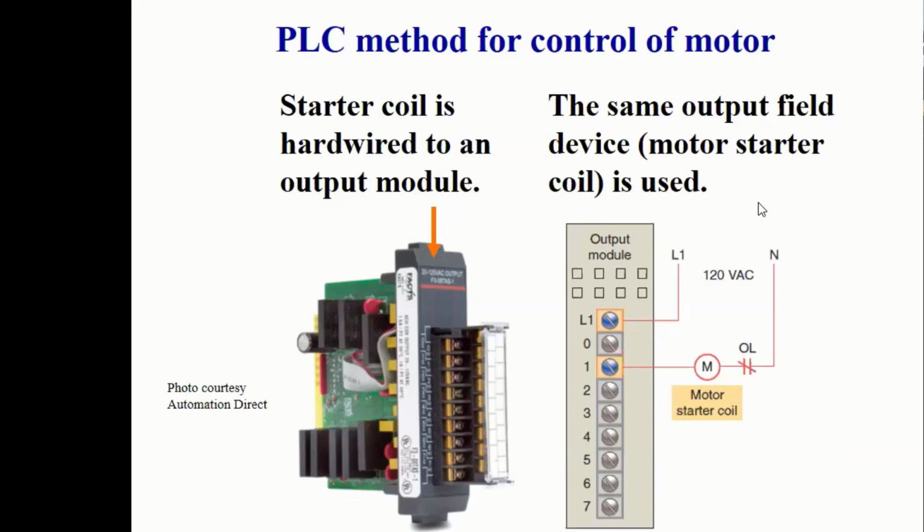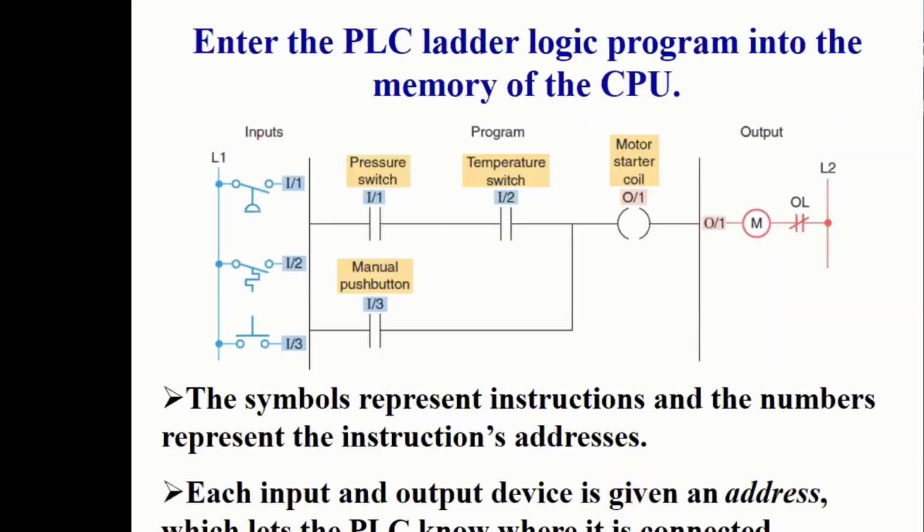All right. And again, we want to send a low power electrical signal, 120 VAC at the most, that will control that thing that controls the big load, right? So in this case, it's a motor core starter that actually is the main element to actuate or activate, whether that's a 2-phase, 3-phase motor or something like that.